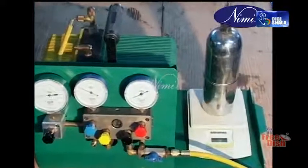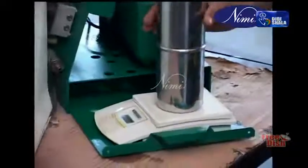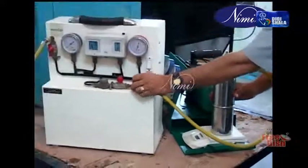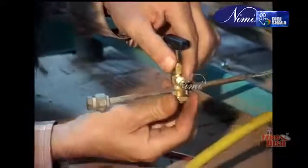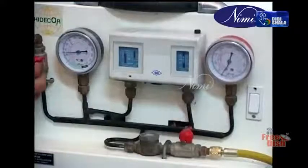And wait. Third, put the cylinder on a weighing machine and connect it with the recovery machine. And fourth, position the piercing valve on the process tube of the system and connect it with the LP gauge port of the manifold through a charging line.